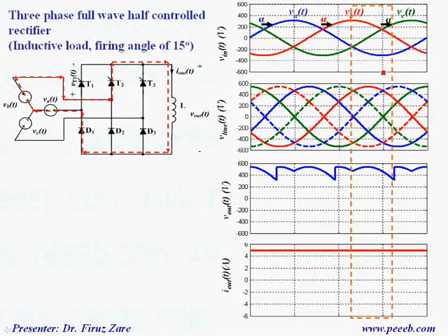So again for this cycle, because still phase B is connected to that terminal, that means T2 is on. So here we have phase B, and because over that cycle phase A is lower than phase C, this diode conducts. So in this case phase A is connected to this terminal. So we have this line voltage across the load.